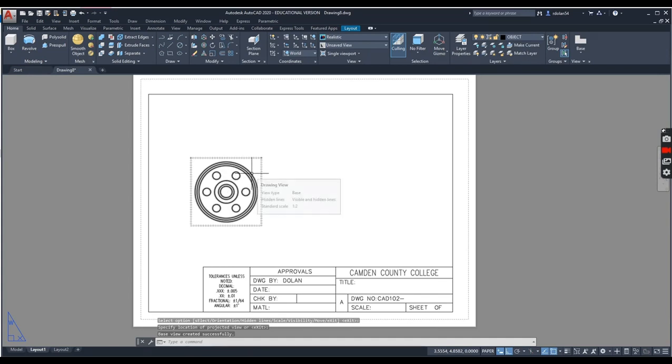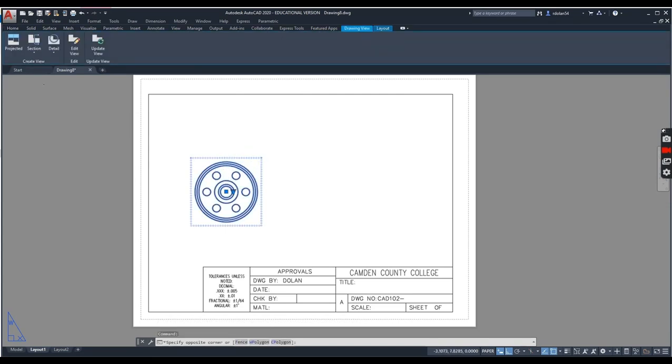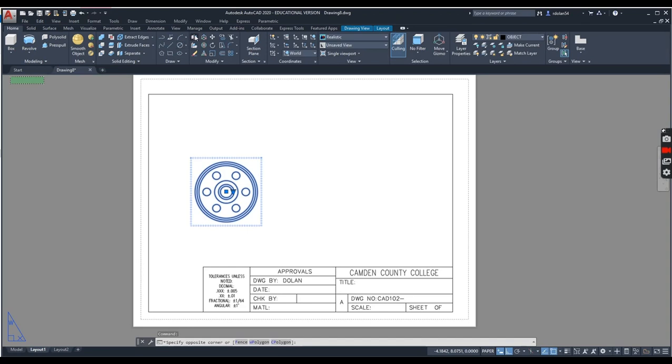If you notice in the book, we have one of the holes right at 90 degrees here. To do that, I can go into the rotate command. If I have mine selected, I'll just go here again to the rotate command. I will select this, pick the center of the circle here, and rotate it 30 degrees. That puts it where I want it.